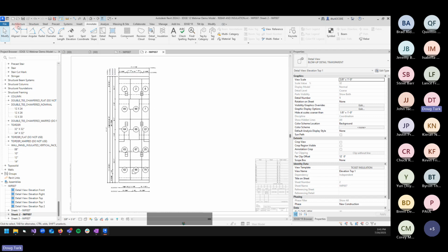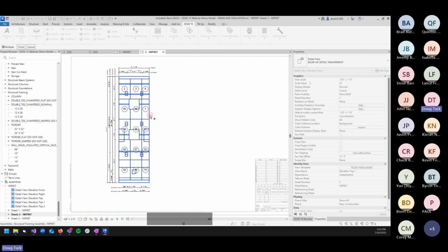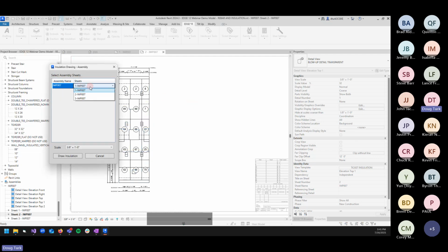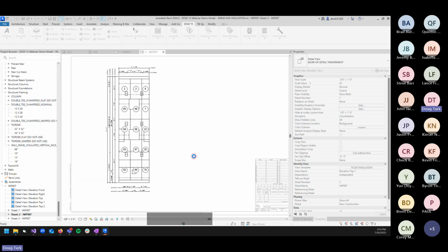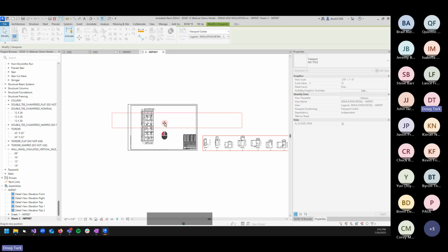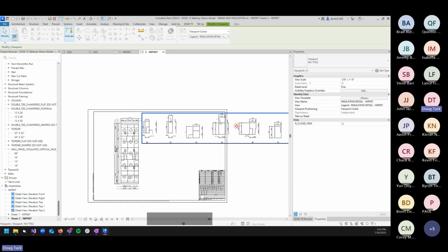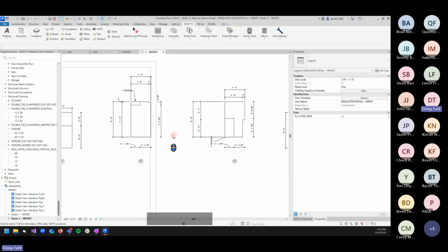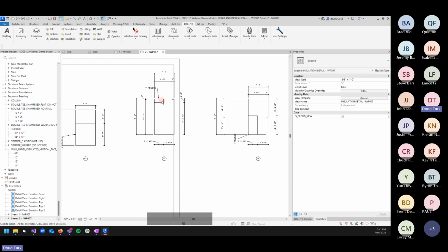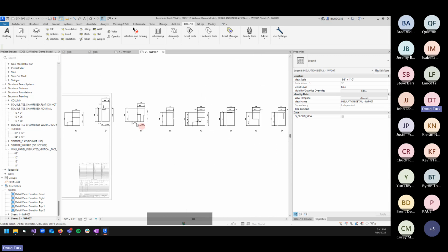Like I mentioned before, we can come in here to the insulation tools, run the insulation drawing for assembly, tell it we want to do it for that one, and then finish. Let's place that on sheet number 2 for this assembly. Draw. Again, it doesn't really know how to fit it onto the sheet, but it's going to hand you the drawings and then you can space these out however you see fit. This is going to show the dimensions of the insulation, any recesses that are cut in it, as well as the mark of the piece that you're looking at.